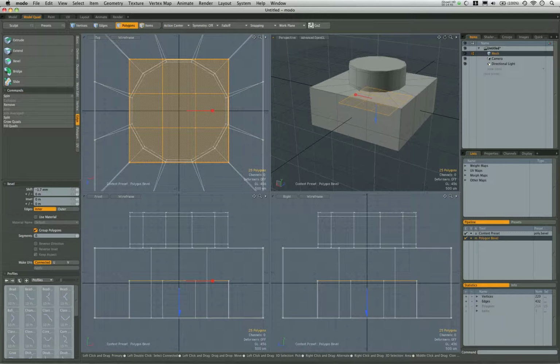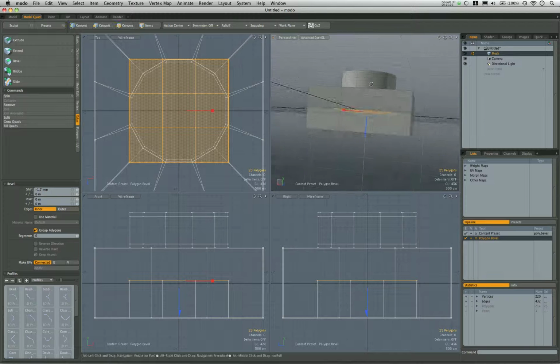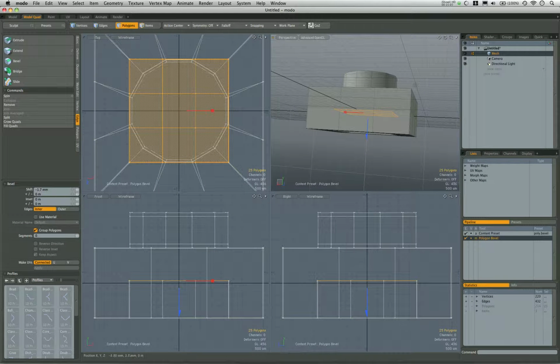So you don't want to have clear pieces where you can see the top of the bump on one piece inside of another piece, and you actually see it crossing over surfaces. It's not going to look as realistic. Plus, if you put some pieces together and look, there is a little bit of clearance. So I'm going to choose to make that just 0.1 millimeters difference. So we have a little bit of space without it being too much.